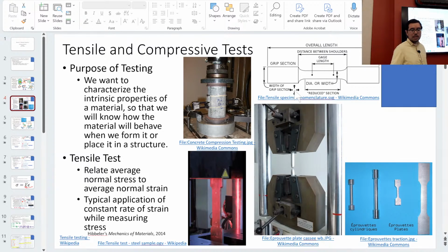The reason there's this curve here, and we don't cover this in this course, you'll cover it in design of mechanical components, is so that you avoid a sharp edge. Where there are sharp edges, there's what we call a stress concentration. So the effective stress at an edge ends up being much higher, like a factor of 2, 3, whatever.